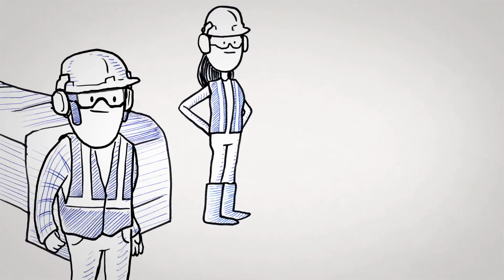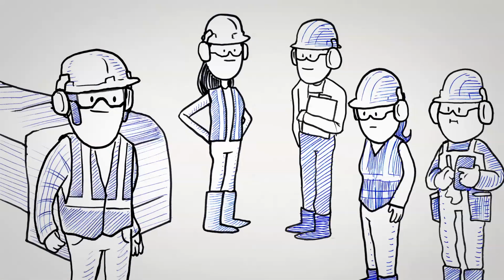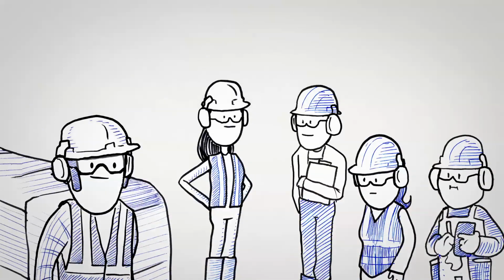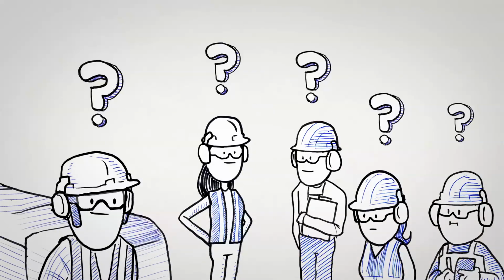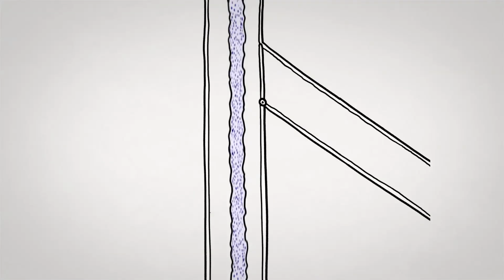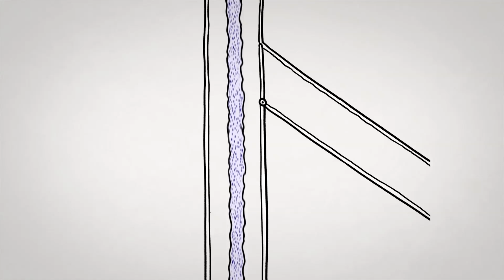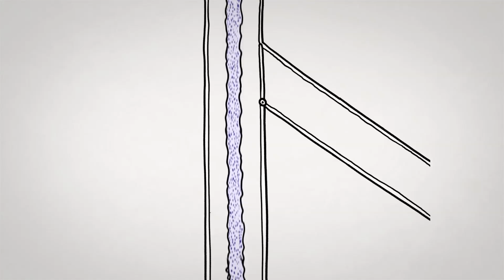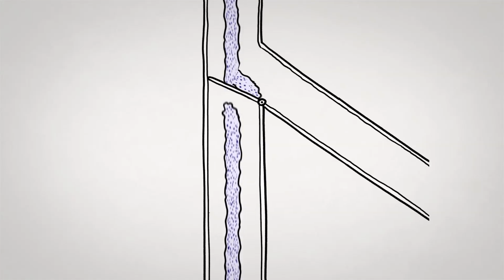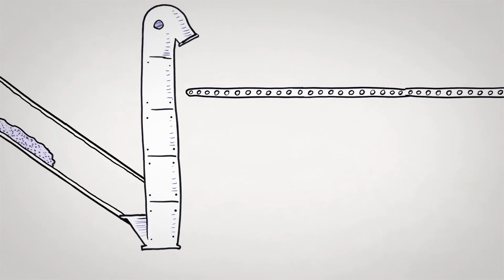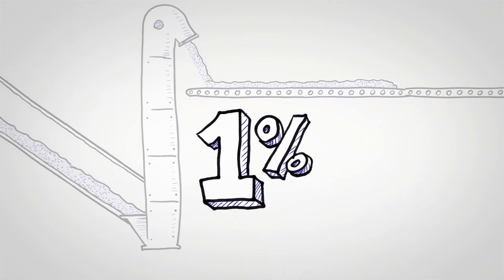Donald gathered a team of operators, maintenance, and engineers, and together brainstormed different possible causes for product not being taken away fast enough. Over the next week, they safely tested all of their theories. They found that when the flapgate was sending meal to the railcar system, the elevator leg couldn't move the product away fast enough. They'd been running stable in the past and had recently increased rate by 1%. Maybe this small increase was just enough to cause this leg to be the bottleneck.